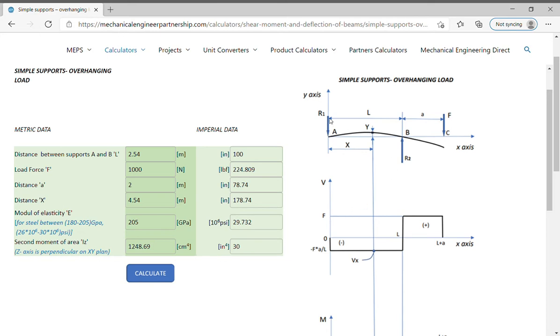The figure shows a beam simply supported by reactions R1 and R2 and loaded by one force F located at a distance from the ends of the beam, at point C. How are the shear force and the bending moment calculated? The following rules are utilized. If the beam is cut at some section located at x and the left-hand portion is removed as a free body, an internal shear force V and bending moment M must act on the cut surface to ensure equilibrium.